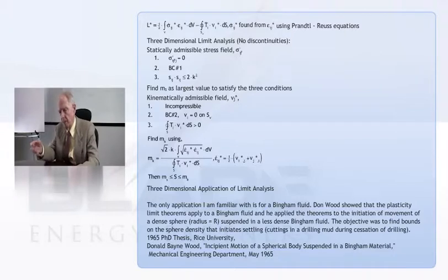really related to a drilling problem where you have cuttings in the annulus of a well, and maybe you've had to stop pumping the mud. So the particle then starts to settle. And one of the characteristics that you put in these fluids is that you don't want particles settling back on top of the bit, and then you can't get the bit started, and it's just one problem after another.